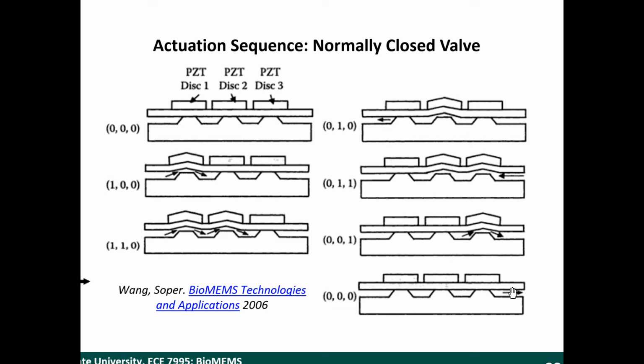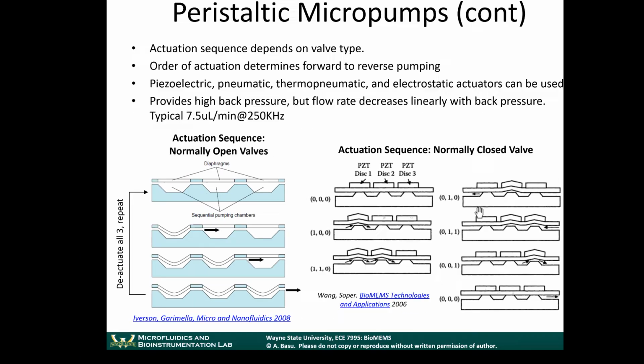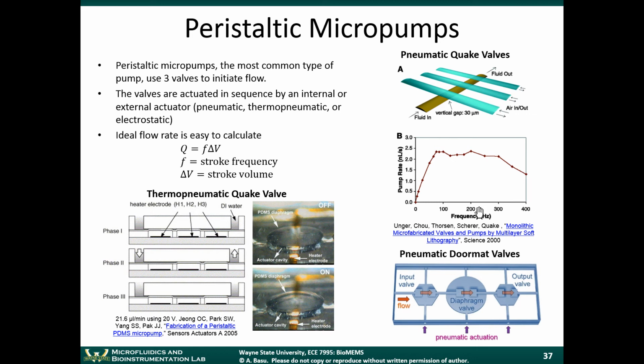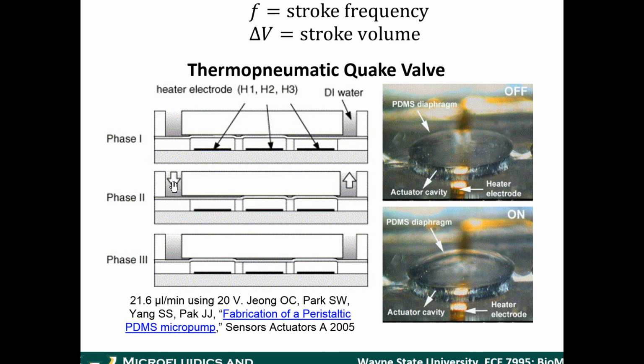Okay, you can look through this on your own. It's relatively intuitive. Just go through the steps on your own one by one. You'll see how it creates this pumping effect. Going back to this earlier slide, you can see here that just a thermopneumatic technique is used. The heaters are controlled in sequence to create the peristaltic pumping effect.